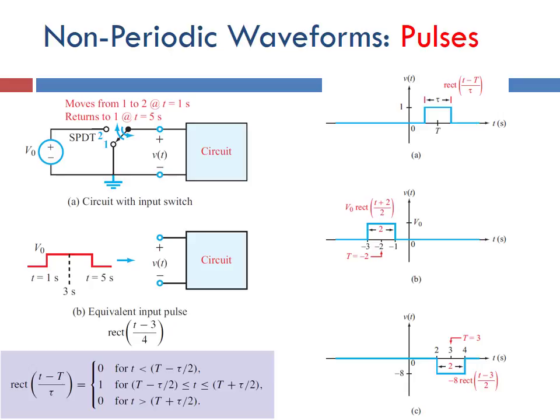So let's look at A. If I have circuit A, which is a power supply with a single pole double throw switch, and I all of a sudden switch it, what's going to happen? If I switch it on and off real fast for 1 second, you're going to create a pulse because you're going to have power going into your circuit, and then it's going to go back off again. And so that's going to generate the red pulse that you see underneath there.